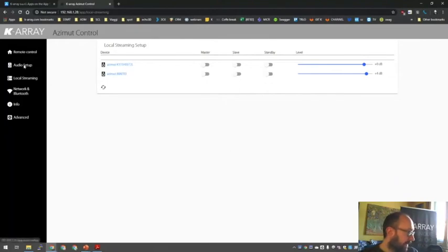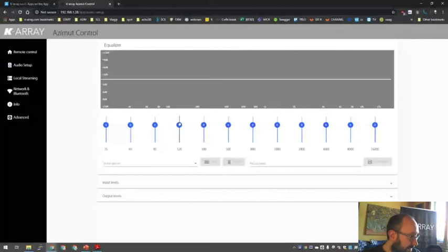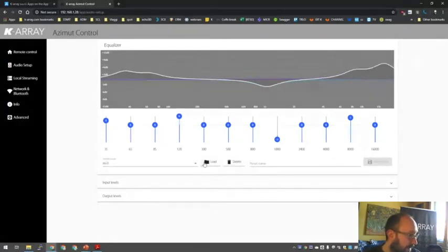Then, audio part, you got a graphic equalizer with a strange number of bands, basically because we wanted to give some more detail in the mid-low area, which is usually what you need the most to do room correction. And you can do whatever you want. Basically, this is. You can save and recall presets, in this case.